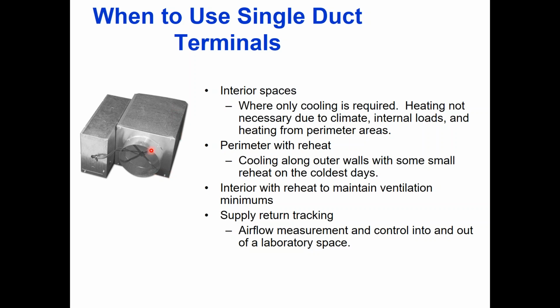Typically, traditionally anyway, upstream of the VAV box was medium pressure ductwork, and downstream was a low pressure ductwork system. So if you're looking at the SMACNA classes, that would be the typical scenario. Usually on the inlet of the VAV box, we will have 4 to 6 feet of flex duct coming in. We don't want 50 feet of flex duct. That's ridiculous from a static pressure resistance standpoint.